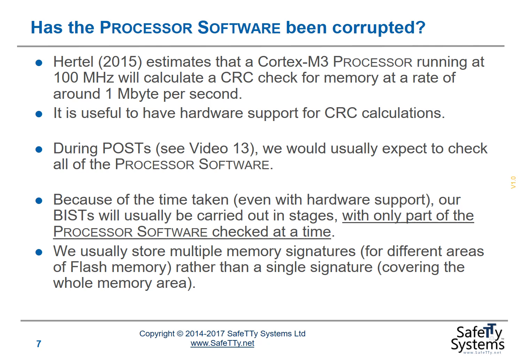During power-on self-tests, we would usually check all of the processor software. Because of the time taken, even with hardware support, our built-in self-tests will usually be carried out in stages, with only part of the processor software checked at a time. Please note that we'll discuss BISTs in general in detail in the next video.